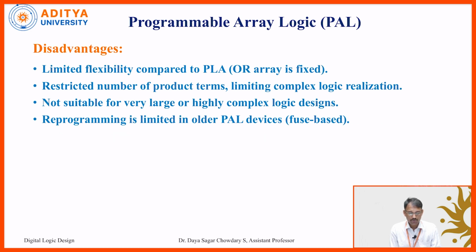So coming to the disadvantages: limited flexibility compared to PLA. PLA has both AND gates and OR gates programmable, but PAL has only AND gates programmable. So OR is fixed. Also a restricted number of product terms, limiting complex logic realization, so not suitable for very large or highly complex logic circuits or designs, and reprogramming is limited in older PAL devices, which are fuse based.